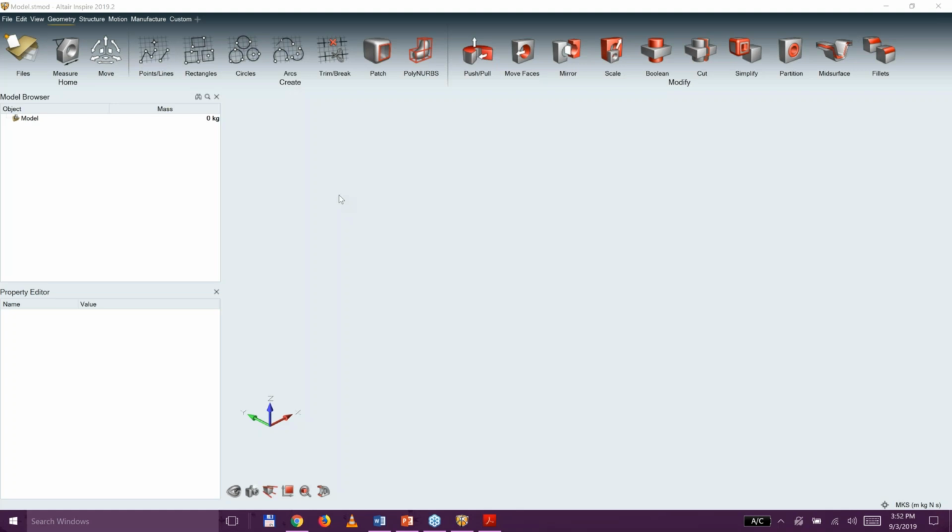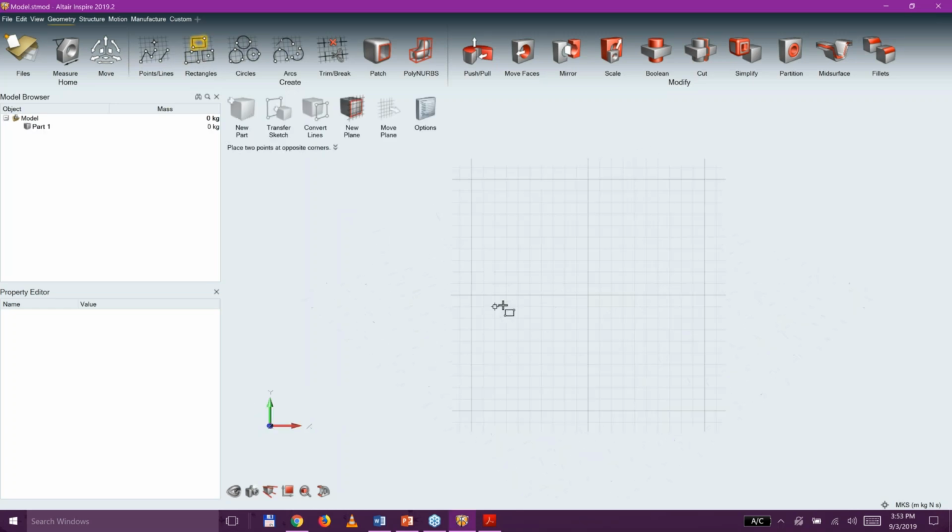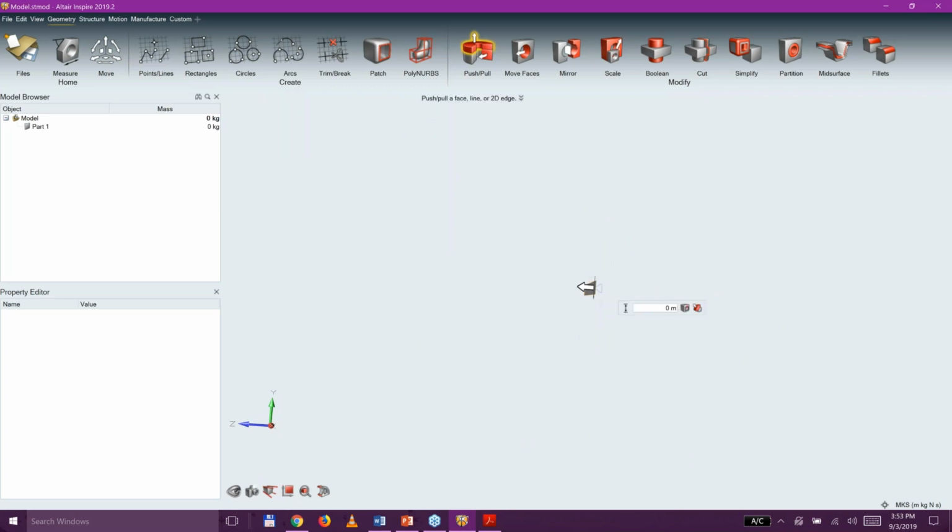But literally, and I know literally is used far too often, but in this case, I do mean literally, the amount of time that it took me to just make that explanation, I could have a cantilever beam analysis running in Inspire here. And I don't even have to go to a CAD system first. I'm just going to come up here to my sketching tool. I'm going to sketch a little bar like that. We'll just leave the values what they are. And now I exit out of there and I just drag that across, and we'll say that we want this to be, I don't know, 3 meters long.